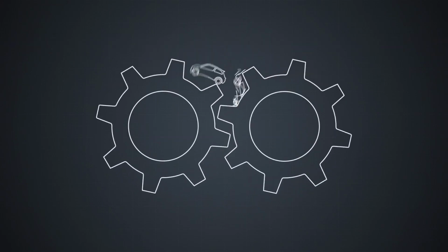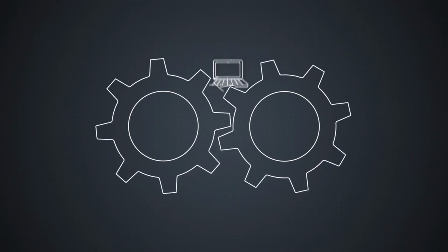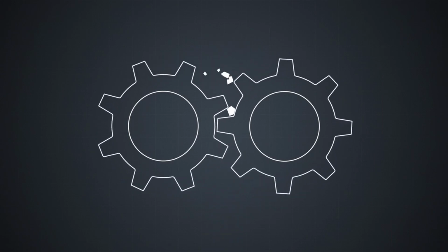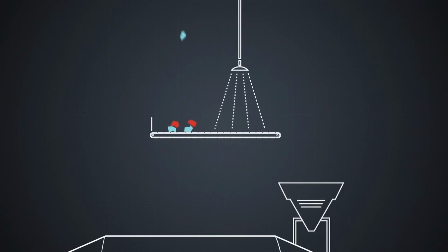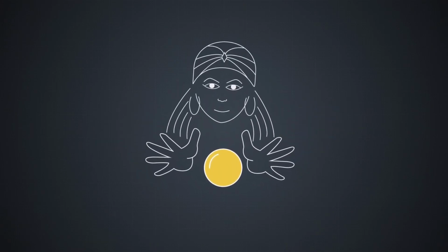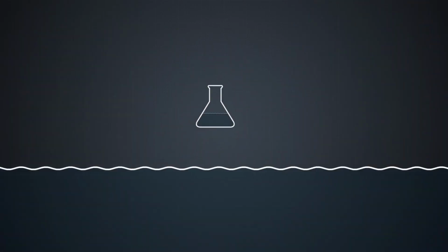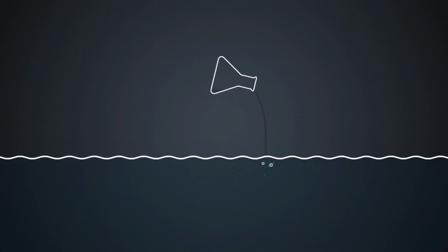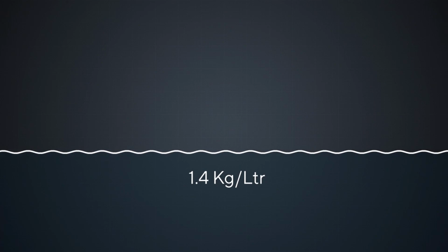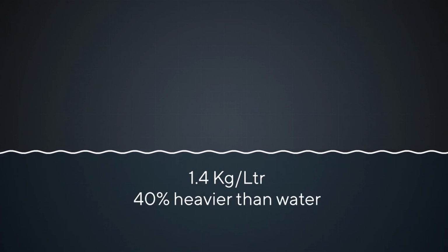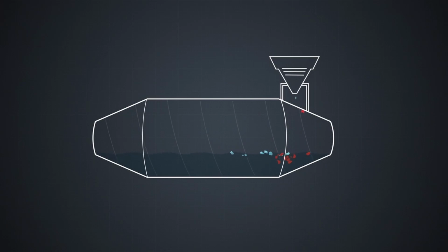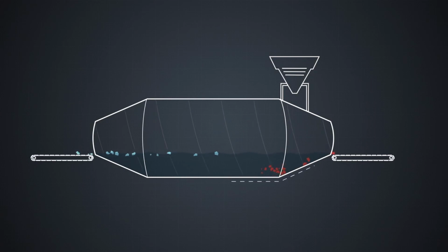Guys, what do we do? HPGR, crush the material, any kind of material. And after comminution comes what? They wash the material, and then they perform some kind of sorting. And after, chemicals. We have to add chemicals because we're talking about recycling. Take a look at this. They put 1.4 kilograms per liter, and then they have dense media separation because they are using that iron silicon alloy that I mentioned to you. But they are also using what? Plastics.